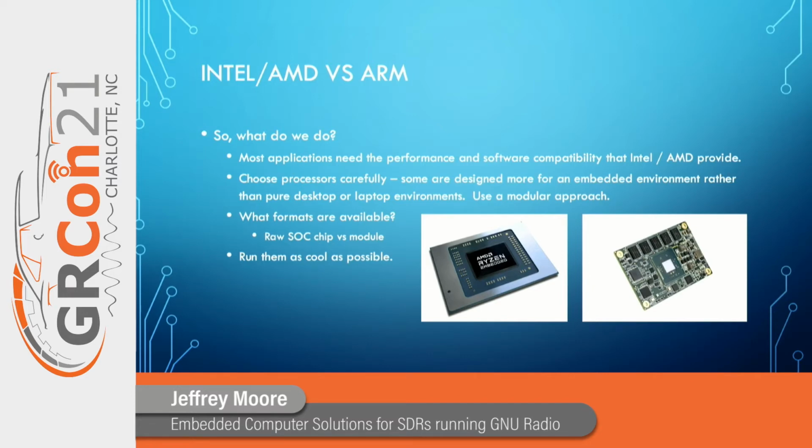But that 0.9 volts can vary by quote unquote software control from the chip between 0.75 or 0.8 volts and 1.1 volts. And it's the firmware, I don't even know if you call it firmware, but the silicon in that chip that decides what voltage it's going to run at. And that's how they try to manage power and boost performance.